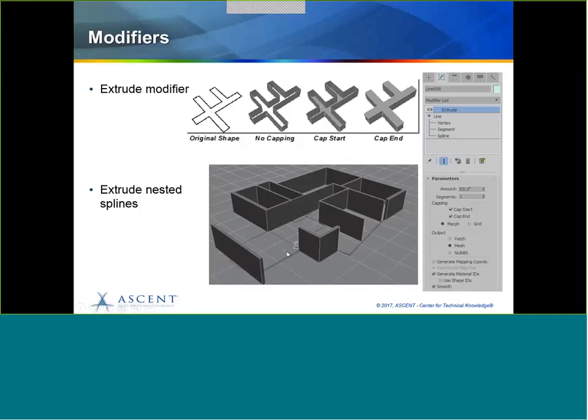And then we have those complex splines. Sometimes we have the 2D shapes in the form of complex splines, which are combined as 2D objects, and these are called nested splines right here on the screen. When extruding a nested spline, which is when we extrude it here, you can see we have extruded it, the enclosed areas form solid masses. This is extremely useful for modeling wall systems and similar kind of geometry in 3ds Max software.